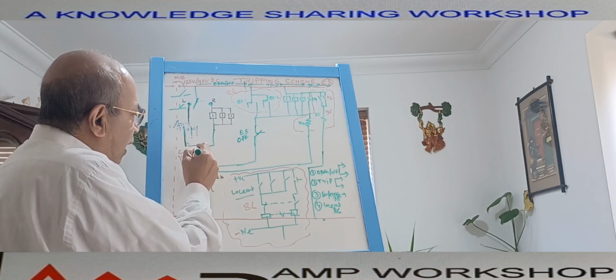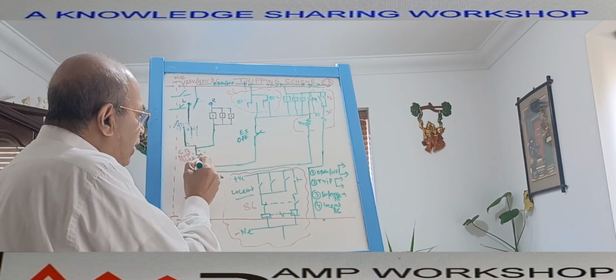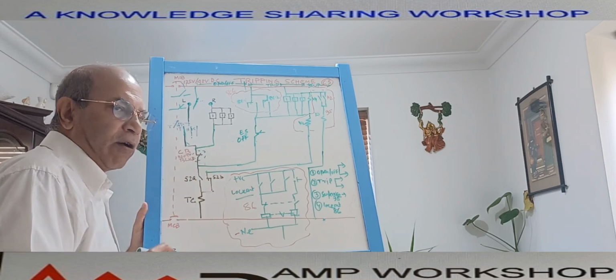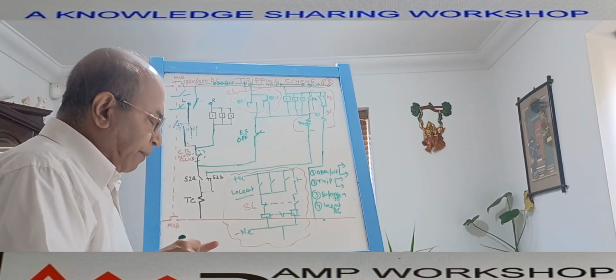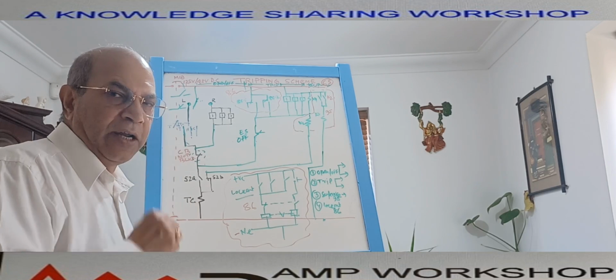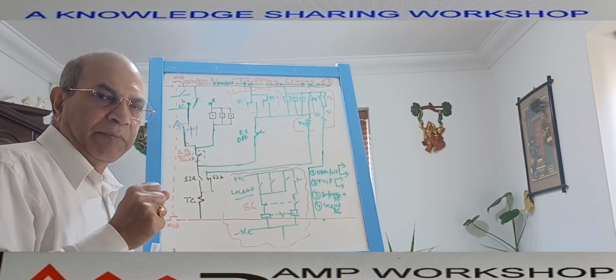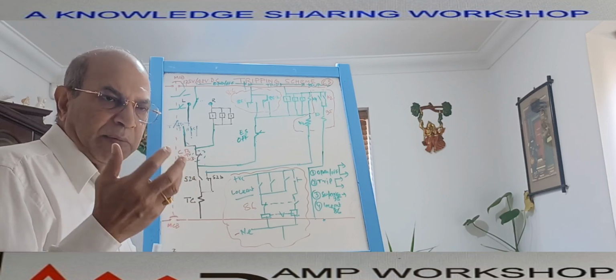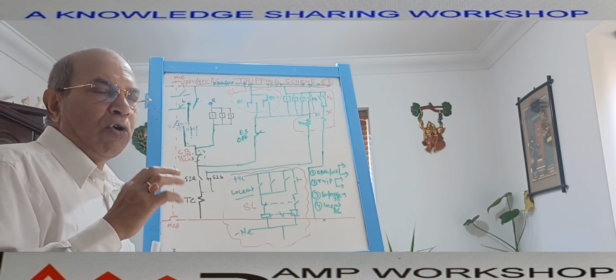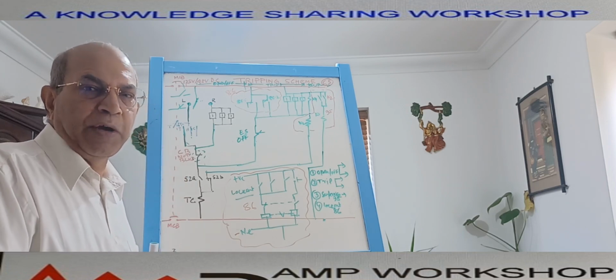So this circuit is coming over here. There is a small interlock we have put over here. For the case of high voltage and extra high voltage circuit breakers, there is an operating handle. Sometimes we need to block the circuit breaker tripping operation for testing, maintenance or some other purpose.